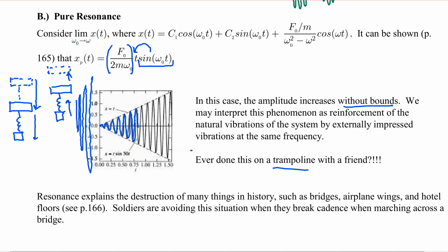One of our instructors in engineering at Amarillo College, who used to practice engineering professionally, said this happened in a simple air conditioning unit that they had installed in one of their buildings. There was a case of resonance. The pipes were oscillating at the same frequency as their forcing function, and it totally destroyed their system. They understood that it was due to resonance. The frequencies were matching, reinforcing each other, destroying the mechanical system.